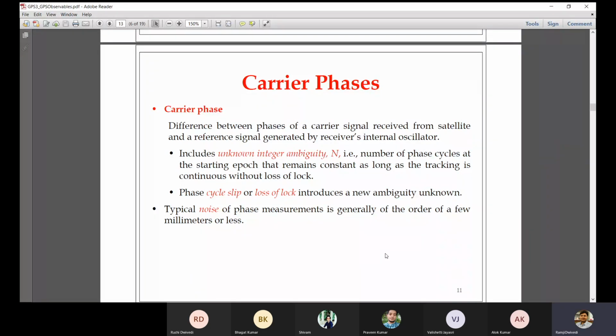So all these parallel steps are following, but carrier phase measurements are ambiguous in nature. That means until you resolve this ambiguity, you cannot get the precise solution. For code pseudo ranges, you immediately get the solution, but it is less precise. So code pseudo ranges will give you an instant solution. Within a few seconds on your screen, you will get latitude, longitude, and height.